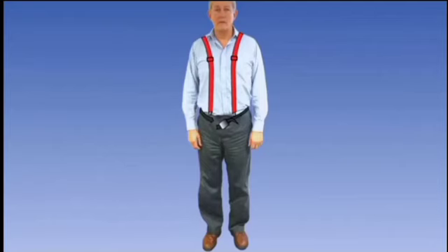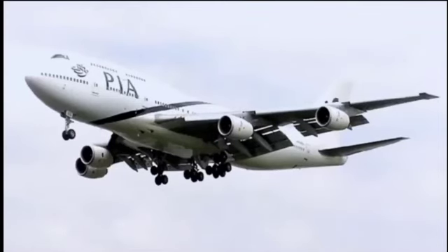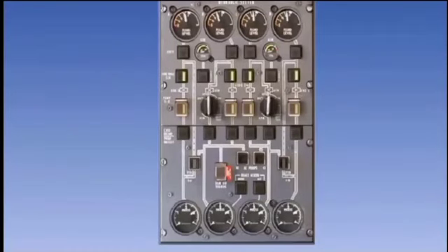The structural subsystems of aircraft are tested for proven reliability so that multiple independent failure conditions are unlikely to occur on the same flight. Airlines with large twin-engine airplanes for extended range operations have to continually monitor and prove their engines' reliability in order to be allowed to operate. So failure warning systems are provided for the crew to be aware of such failures.